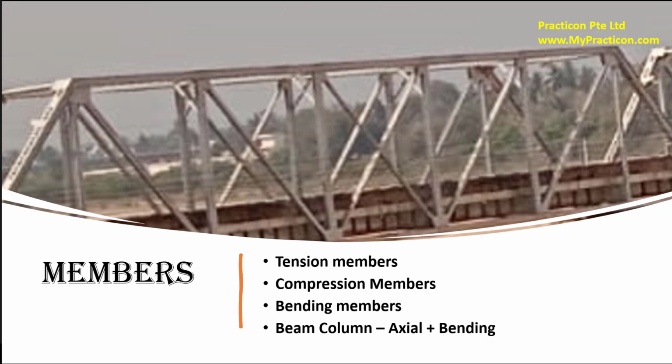If any member is subjected to axial force together with bending, we call it a beam column member, which normally is checked for axial plus bending. Once this identification has been done, appropriate design equations are used to calculate the strength of those members and make sure they are capable of taking the external forces. So with this, members will be designed.